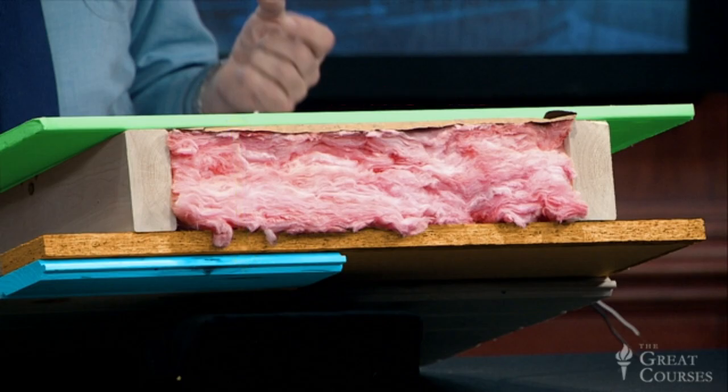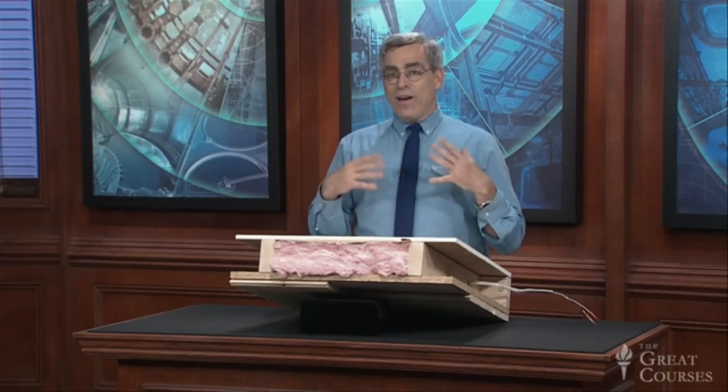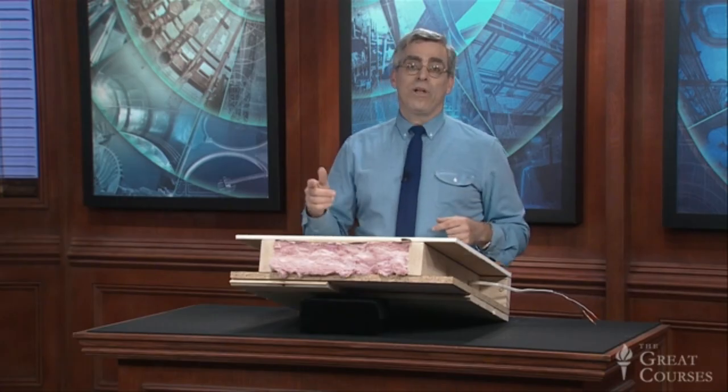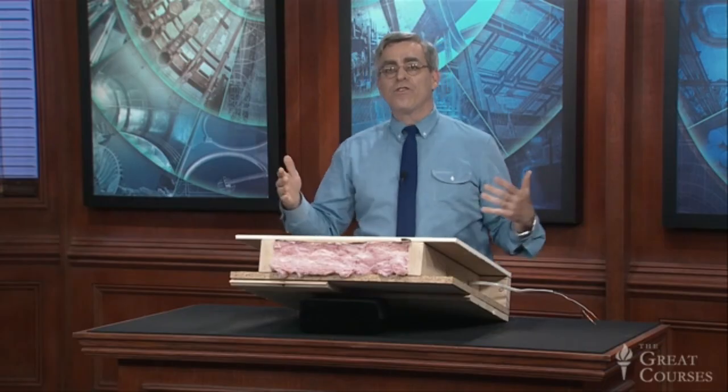Now let's look just a few inches away along this path through the stud. This path consists of 5 inches of solid wood, siding, sheathing, and stud, and then 1/2 inch of drywall. And so when we add it all together, the total R value along this path is only 7.6. This is a thermal bridge, and it occurs wherever studs, top plates, sills, or headers provide a low R pathway for heat transfer through the full thickness of the wall.